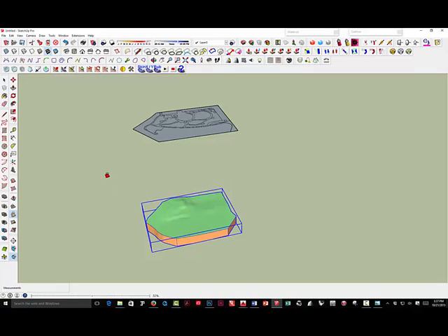Now you'll notice at the bottom, it's making progress here. So I've got one good piece of advice, and that is don't click, don't touch anything, don't do anything until it's done figuring this out. If you do, you'll probably make SketchUp crash. It's never had very good error trapping when it comes to the draping function. But what it's doing is figuring out how all those curvilinear lines fit onto that landform below.